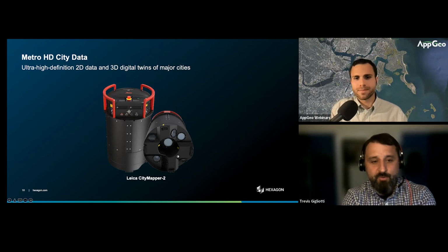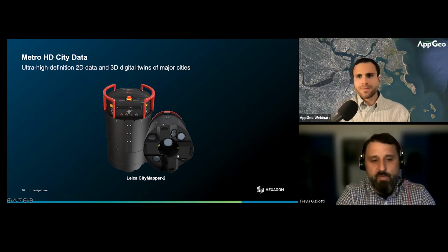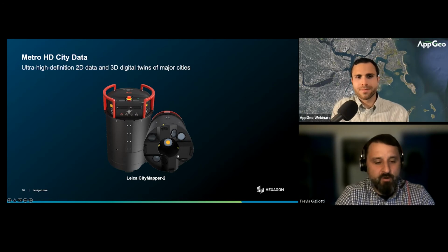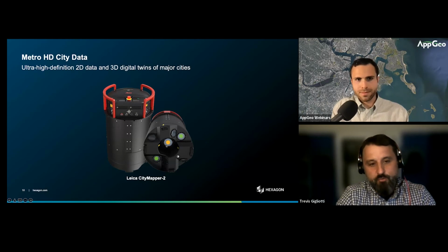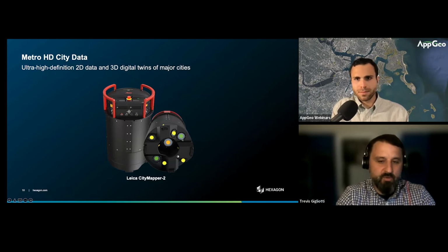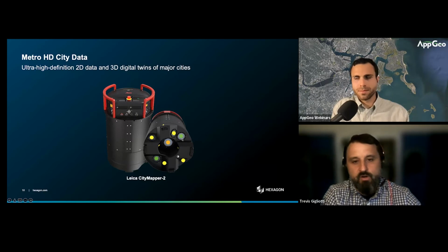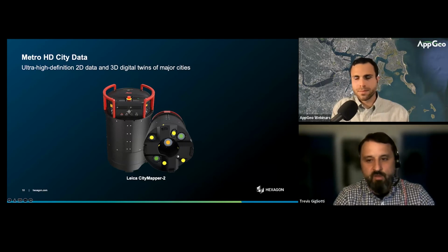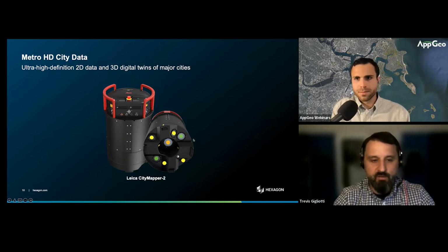That's absolutely right. So if we can animate the slide slowly, as I mentioned, the things we see are our 2 megahertz LiDAR system in the center. We see our two nadir-looking cameras at a 45-degree axis from the LiDAR. And then if we click through one more time, we see the 4 oblique cameras that are oriented in the cardinal directions with respect to the line of flight.